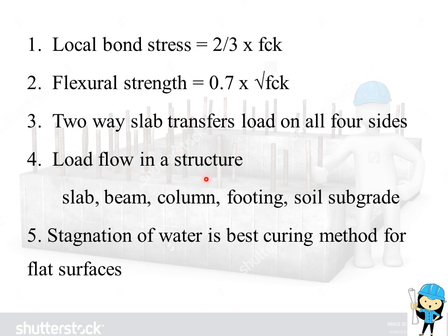Load flow in a structure. So the basic load flow in a structure is from slab to beam, beam to column, then to footing, and finally to the soil subgrade. Stagnation of water is the best curing method for flat surfaces.